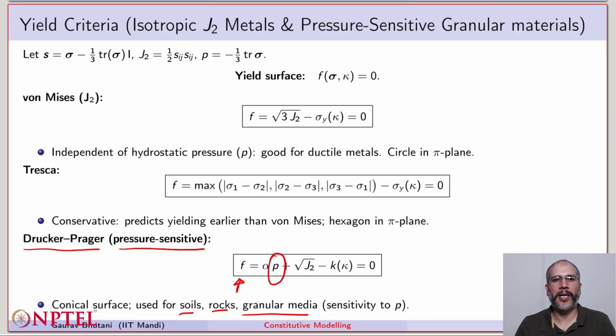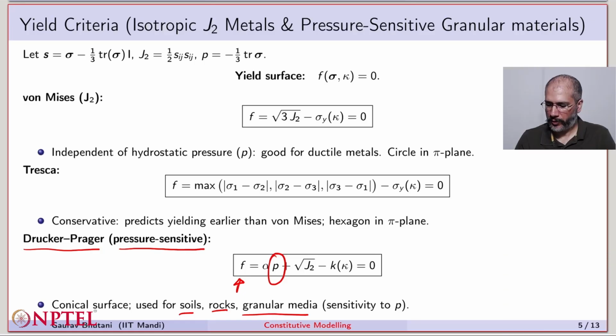Now think of some granular materials, let's say soil. So if you take a cube of soil like this and you apply some shear stress on the top, then you will see that the cube of soil will shear, or if you think of the cube as just one material, you will see the material plastically flowing.